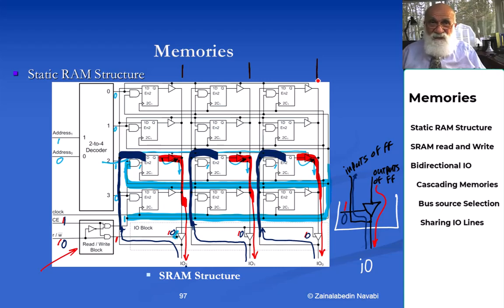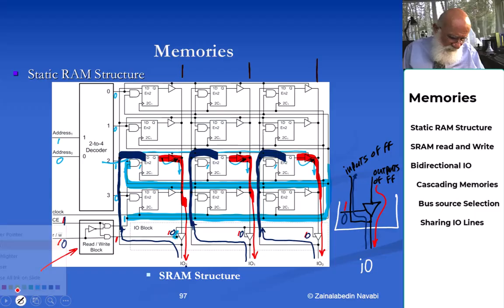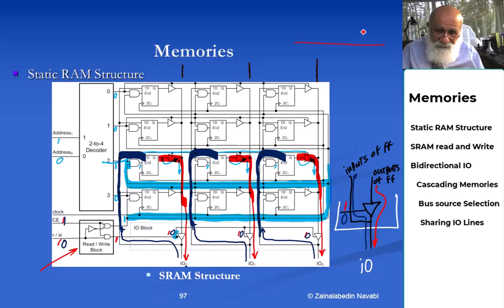This is as much as I want to get into memories, but then there are RAMs that do not really need all those flip-flops and all the gates and everything. They have something like a, let me show you this. They have a word line and a bit line, and then there is only one transistor, and then the capacitor here is really what stores the data into that memory bit. This is the word line.